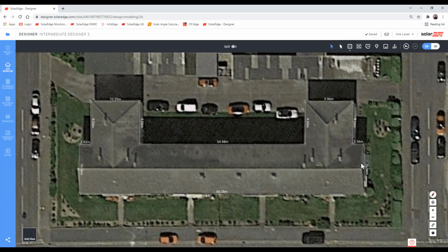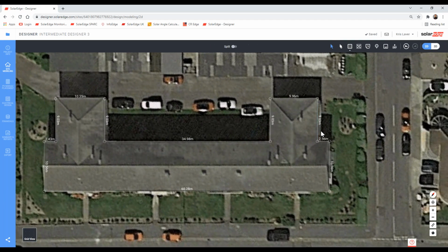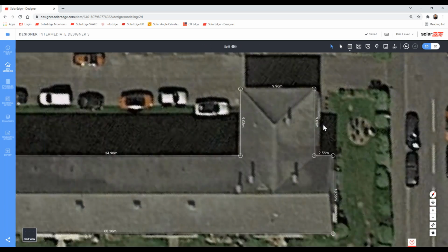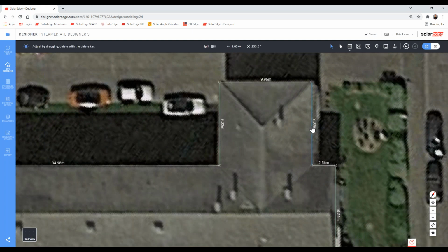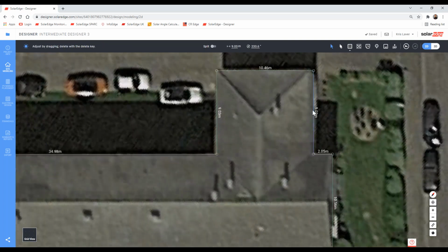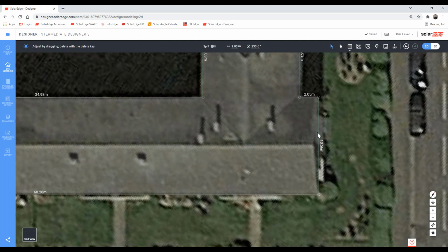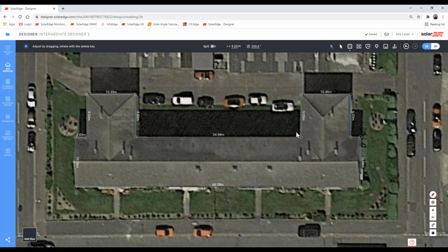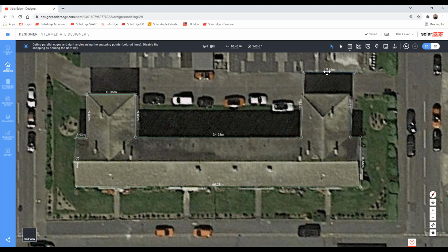So it's quite subjective. The image, that one, is slightly skewed. You can see some of the gable end here. But if you do want to move a line, then yes, you can simply click there, click once, hold, and then simply drag the line. Let's say it's there, for example. I'm trying to miss this section because it's skewed. You can see some of the gable wall there, for example. Again, if you wanted to move this line, you click once and hold it and drag it up there, but you can drag it off of your 90. So it will snap ever so subtly when the 90-degree angles are there.